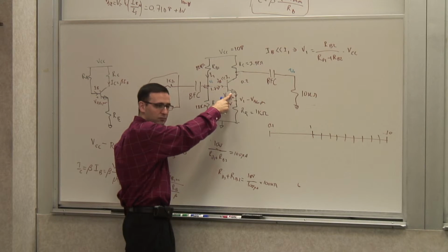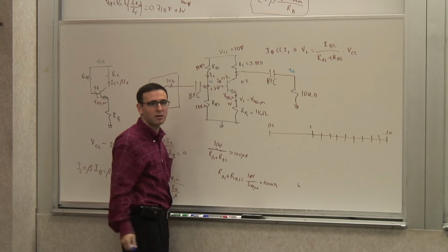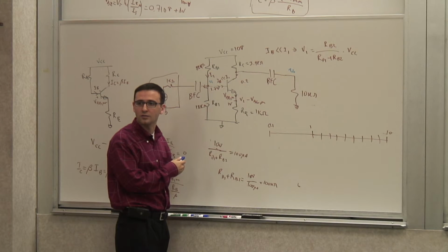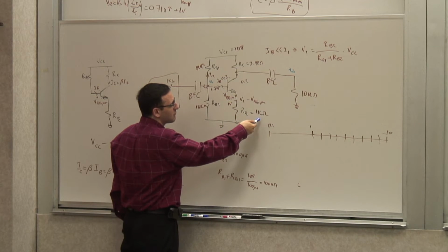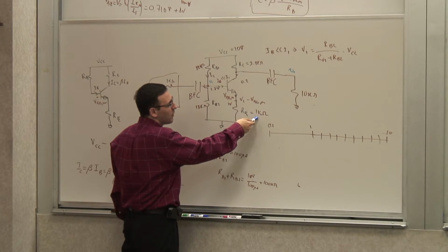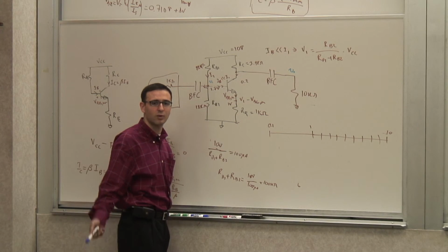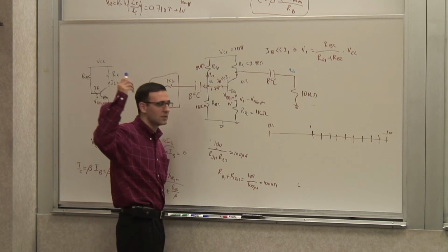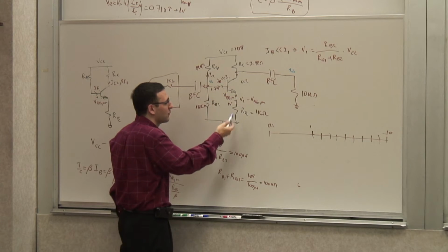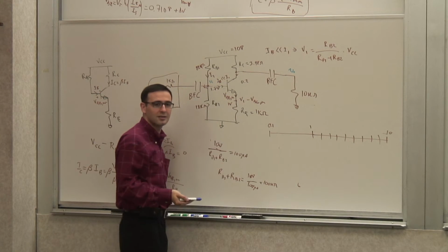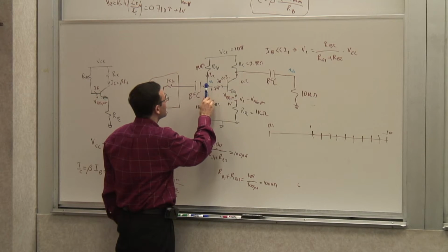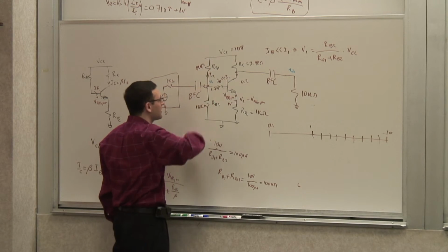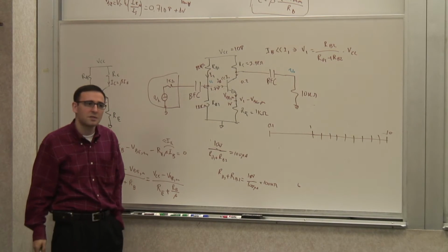So it's about 25 ohms at 1 milliamp, plus 1 kilo ohm. That gets multiplied by 100, right? So that gives me about 102 kilo ohms. Ballpark 100 kilo, right? I don't even think about r_pi. Ballpark is about this guy times beta. So I see 100 kilo ohm, I see 82 kilo ohm, and I see 18 kilo ohms. So it's a parallel combination of those.